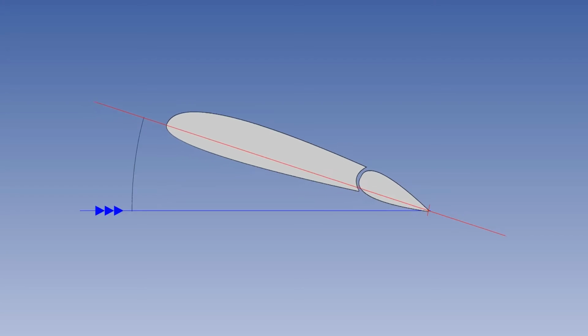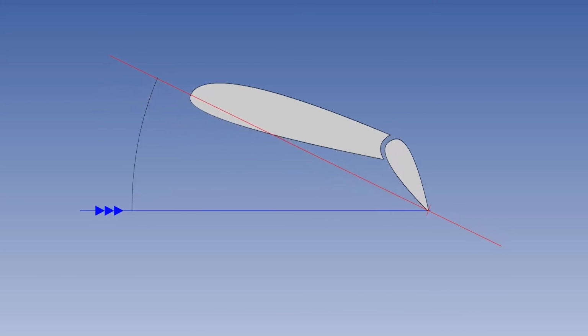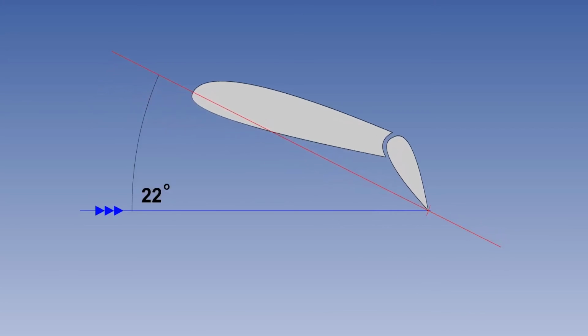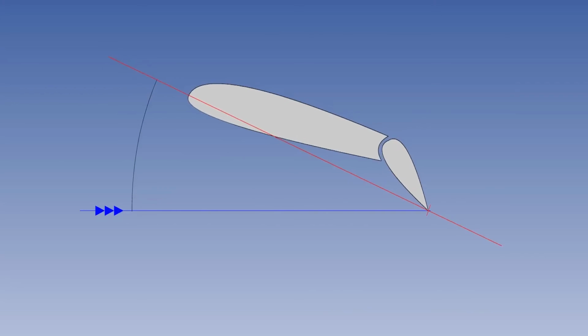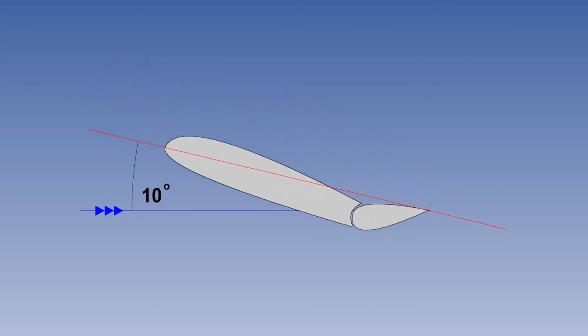Trying to lift a dropping wing with aileron will increase its angle of attack further, taking it deeper into the stall. At the same time, the upgoing aileron on the opposite wing will decrease its angle of attack, possibly unstalling that wing, which produces more lift and exacerbates the roll already made worse by the changes in effective angle of attack.